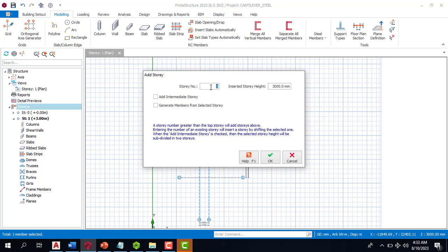The reinforced concrete footing is going to be a story on its own. Then the steel column, the entire overall height of that column, is going to be another story on its own. So that's 2 stories already. For now we are going to type in 2 as the number of stories.